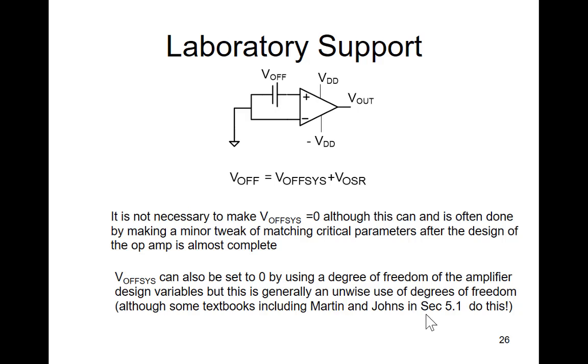Yes? If we really cared about it as a designer and we can't distinguish between the two after, couldn't we exploit some form of an E-trim or a laser trim to try? Yeah, that works. Those work great. It's strictly a cost issue. Anytime you do a trim, unless an electronic trim is something where there is no circuit, no trim bits required, then it's probably acceptable to do it on chip. But otherwise, it gets really expensive.